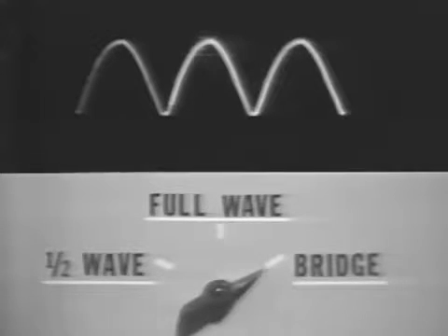And yet, they all operate on the same basic principle, electronic switching of the transformer secondary. We're going to discover this principle by tracing the development of these rectifiers, because by understanding this simple principle, you'll be able to name each component in the bridge rectifier circuit and know exactly what its function is. You'll be able to trace current flow through the circuit. You'll know how to calculate all the voltages in the circuit, and you'll know how to troubleshoot the circuit. All these things you'll learn in this lesson on the bridge rectifier.